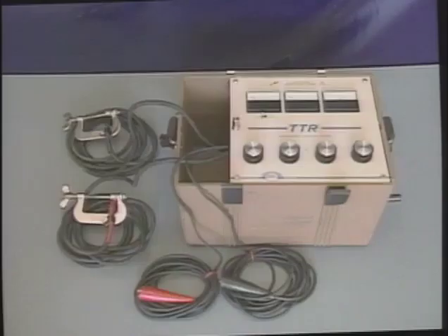Then the turns ratio setting of the reference transformer is noted, because that is also the turns ratio of the power transformer. Now, in looking at the principle of turns ratio testing, we've identified some of the components of the test set. Let's see what these and other components look like on an actual turns ratio test set. Here's a typical turns ratio test set. It may look a little different from the set you use, but it will have the same basic features.